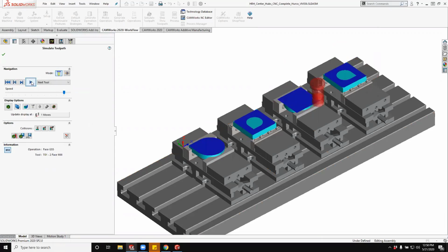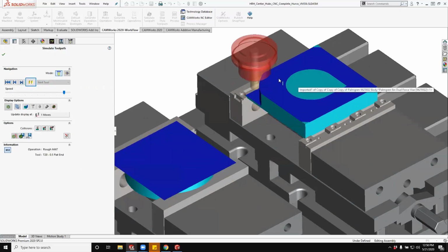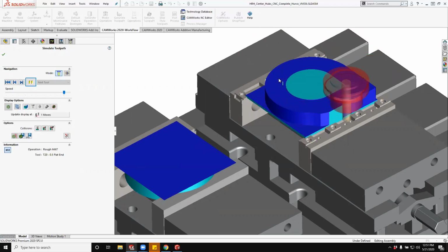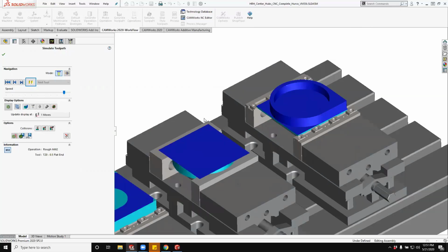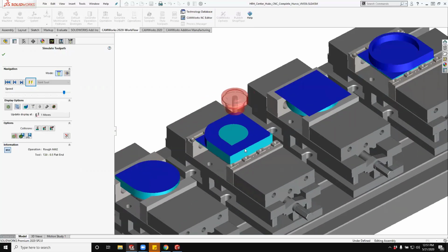So here's my facing. And I was actually using a volume mill facing operation on a couple of these guys as well, just again because that machine doesn't have a lot of horsepower. And then on these guys, I just roughed away the area where it's actually going to be the finished part. And then here would be that volume mill tool path. So it's going in and it kind of scallops off that material. I'm running that at about, I believe, 175, 200 inches a minute full depth, and running about 125 inches a minute to clear that material out right there. And then it's going over here, another volume mill tool path.